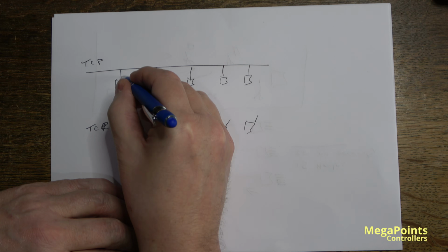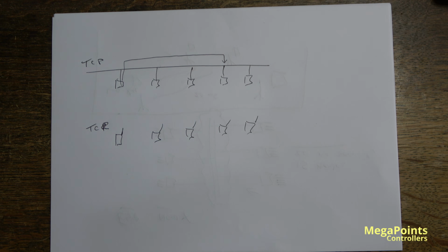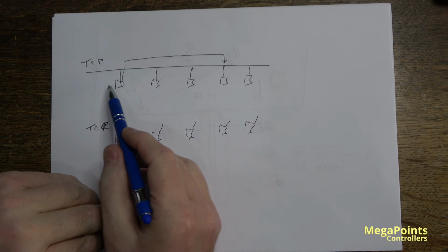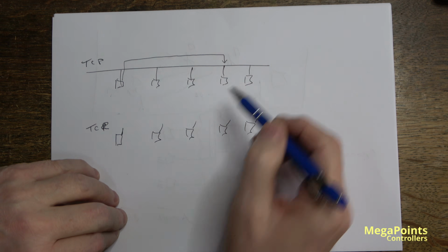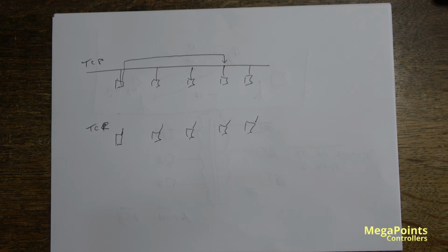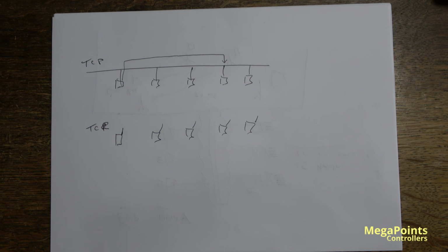It will send a packet from here specifically to another address. And that's a bit like the ESP-NOW. So if I want to send this to all boards, I've got to send an individual packet addressed to the recipient on the network. And that means that my little tiny device is spending more time talking radio than doing useful work.